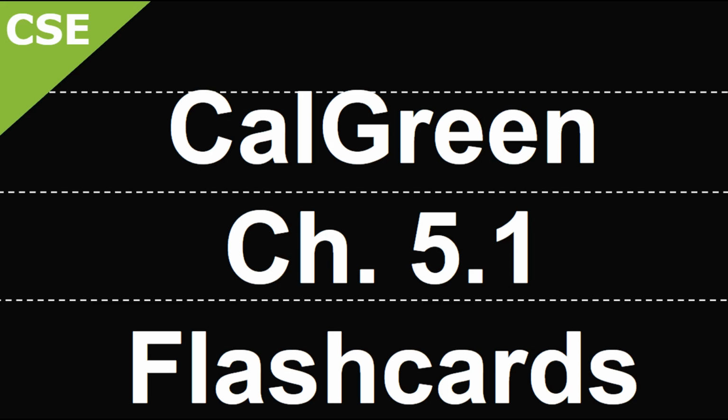If 76 to 100 total number of electric vehicle charging stations, then 1 must be van accessible, 3 standard accessible, and 3 ambulatory. And finally, if you're providing 101 and over total number of EVCS, then 1 plus 1 for each 300 must be van accessible. For standard accessible, 3 plus 1 for each 60. And for ambulatory, 3 plus 1 for each 50. Make sure that you install EV-capable spaces per Chapter 11B near a building's entrance for future compliance with accessible guidelines.